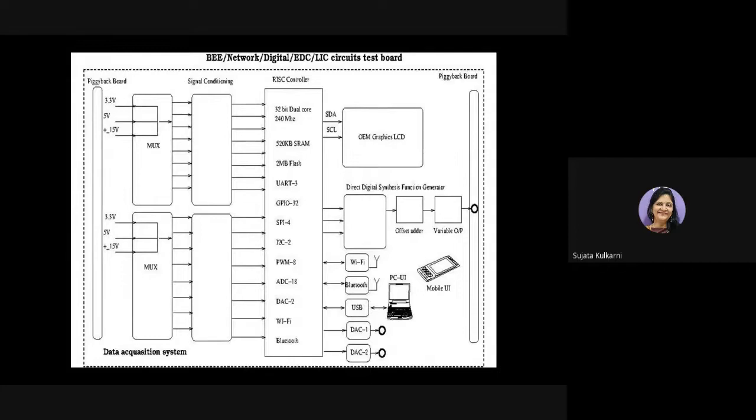So that is another challenge: for the output of the DDS, you should design your own signal conditioning so that it is uplifted up to plus 15 or minus 15, or a DC value. You should be able to add it. That's another requirement you need to fulfill as part of the baseboard. Then about the arbitrary function generator.